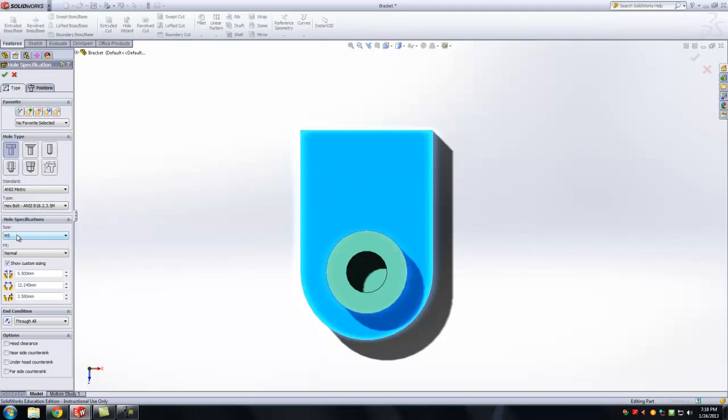All right, then we come to the sizing. Now, SolidWorks has some library of different sizing. So notice if I click on that drop-down menu, I'll see M5, M6, M10. For those of you who don't know what this means, it's approximately the diameter in millimeters. So if it says M10, it's approximately 10 millimeter diameter. Okay? And you're going to see how that is done in a second. So let's go ahead and click on M10 for now. Alright, and we're going to do a normal fit.